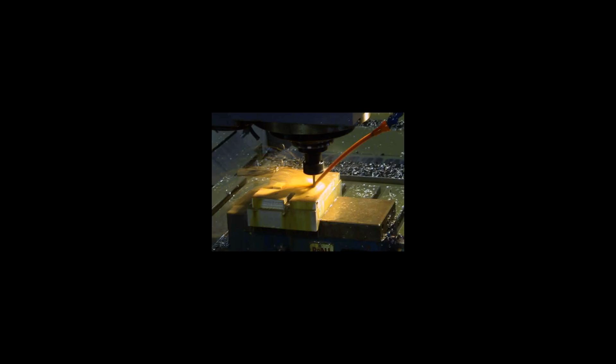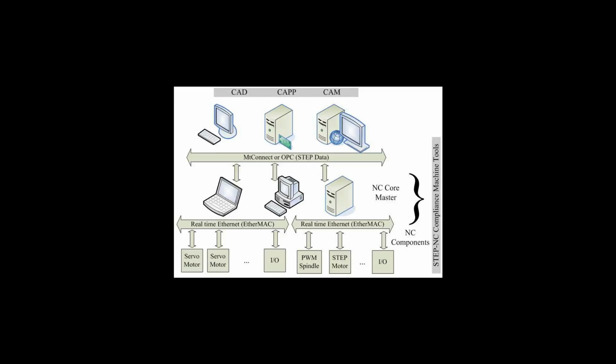4 CAD/CAM systems produced AP238 machining programs for milling a 5-axis test part, and NAS 979 circle, diamond, square with an inverted NAS 979 cone test in the center. Each run on a pair of CNCs configured for completely different machine geometries: AB tool tilt versus BC table tilt. In addition, Boeing cut parts on a variety of machines at their Tulsa facility and a machine at NIST in